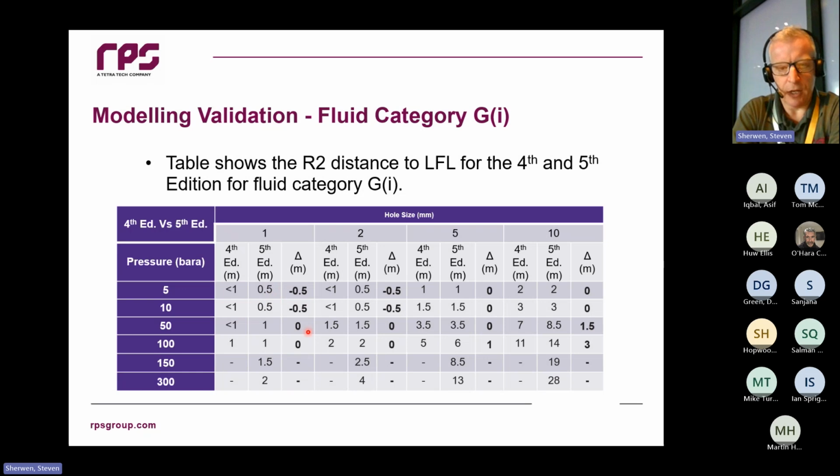Okay. I'll preempt a question that may come up later. How do these figures compare to SR25? Well, SR25 has smaller zones for natural gas, but you've got to compare eggs with eggs. The hole sizes that SR25 uses are much smaller than EI15, because SR25 is industry guidance for basically end users of natural gas. So if you've got boiler houses or furnaces, etc., you're an end user of natural gas and you should be using SR25. EI15 is more for the producers and the processors of natural gas, hence the larger hole sizes and the fact that we don't have zone 2 NEs at these lower pressures.